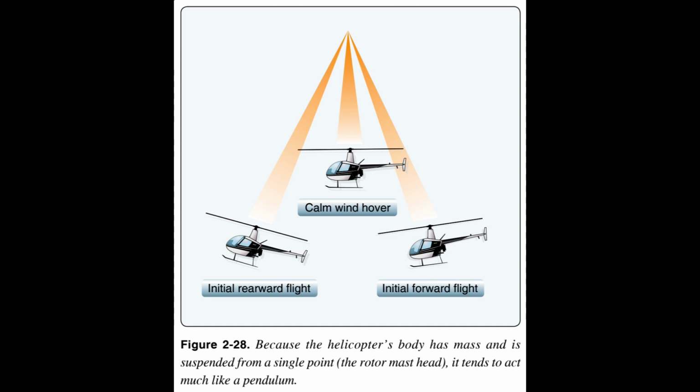Figure 2.28. The horizontal stabilizer helps to level the helicopter in forward flight. However, in rearward flight, the horizontal stabilizer can press the tail downward, resulting in a tail strike if the helicopter is moved rearward into the wind. Normally, with the helicopter mostly into the wind, the horizontal stabilizer experiences less headwind component as the helicopter begins rearward travel, downwind.